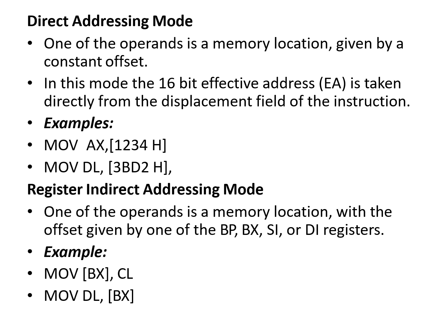Next, register indirect addressing mode. Here the base register BX or base pointer BP, and the index register SI (source index) or DI (destination index), hold the offset value.